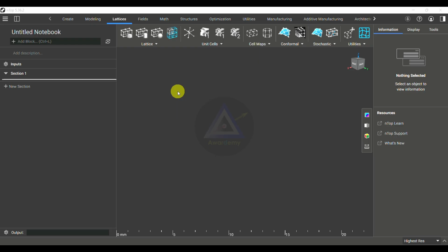So here, two major input parameters we need to give. One is the spherical volume lattice. Suppose we have one entire volume where we use the spherical coordinate system. So using the spherical coordinate system, we have the big volume. Within this spherical volume system, we are going to select some specific shapes, and insert strut-based unit cells. Those unit cells are present within our nTopology software.